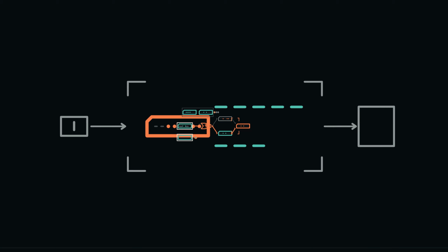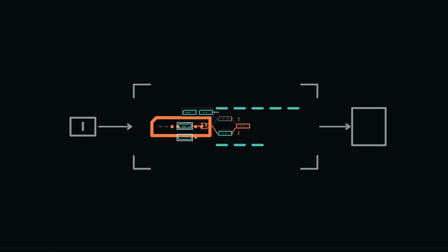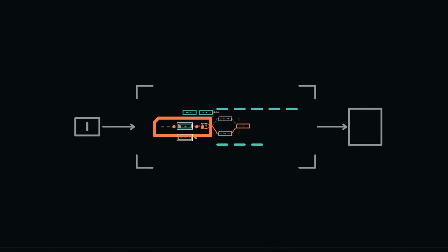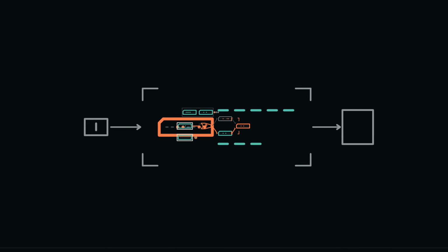An unconditional jump can replace PC with an earlier instruction address. Repetition follows because the new PC causes those bytes to be fetched again. Termination follows because repeated arithmetic eventually changes the tested flag. The machine now chooses what happens next using only stored patterns, exact logic, and committed state. We are ready to view the complete processor as one earned system.